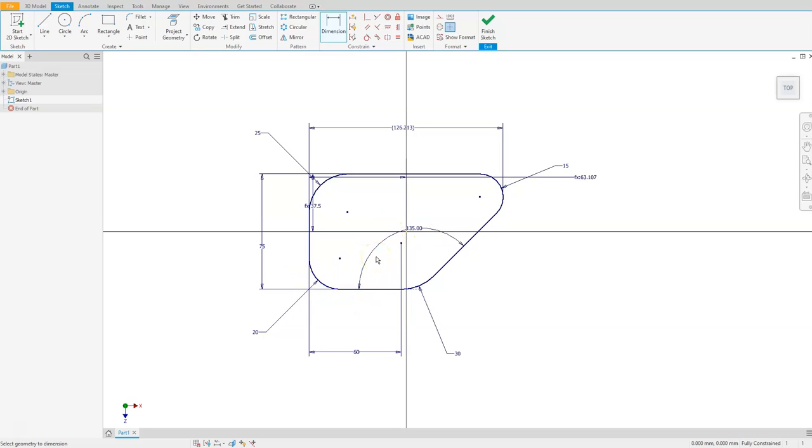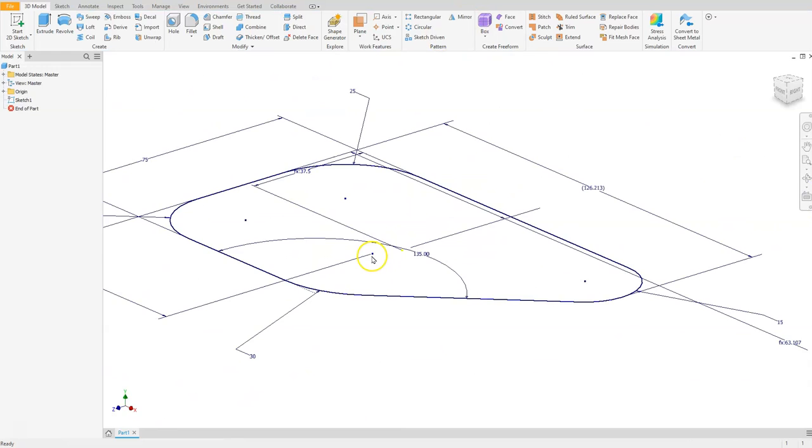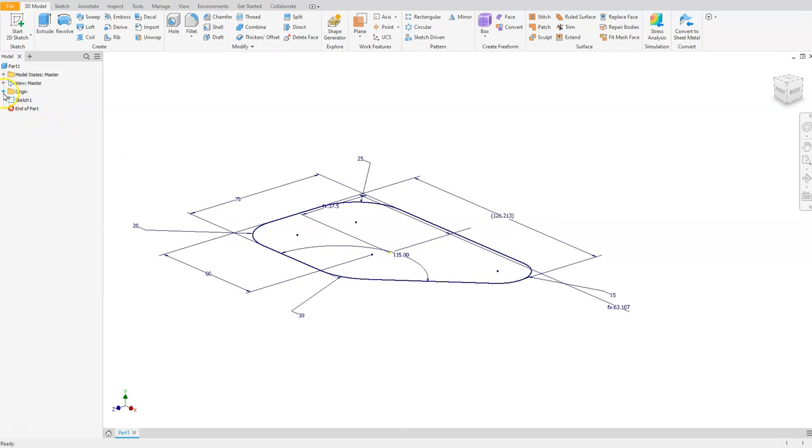That's really important on some applications, especially when you go to create parts and when you're constraining. So it's a very good practice to at least use those center lines or put it in the center origin. And I'll show you a little bit of the reasoning behind it: whenever we create a part, remember that these origin planes are going to run directly in the middle of my part. So that's one of the reasons why sometimes you want to have your parts directly in the center. You're going to see that when we come to constraining and doing other things of that nature, we can actually use those planes as references in our constraints, and it'll make our life a lot easier, especially when we want to get to the center of that part.